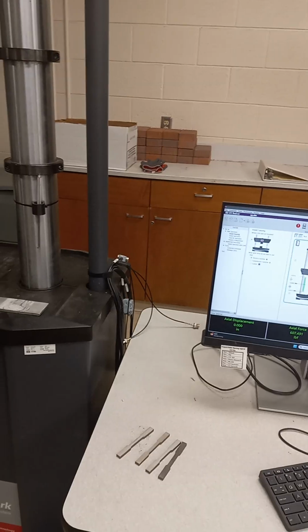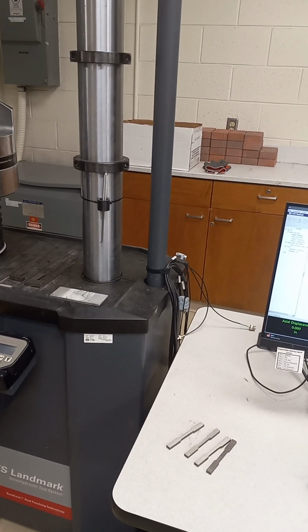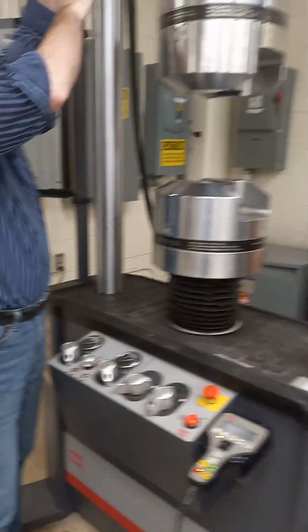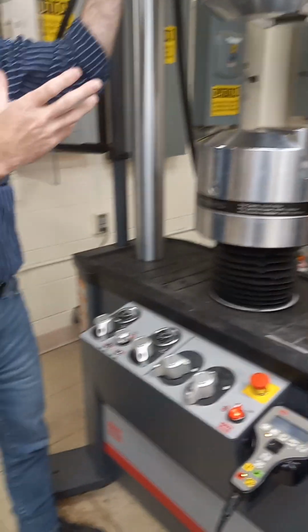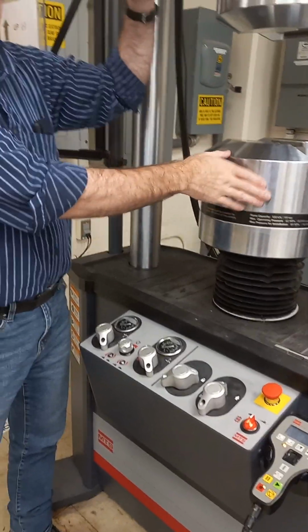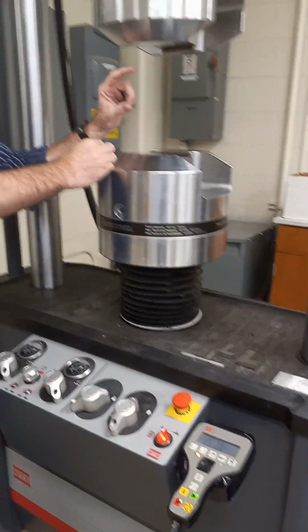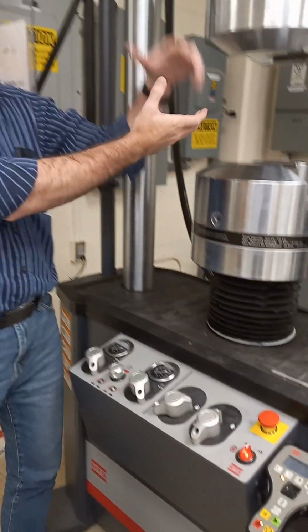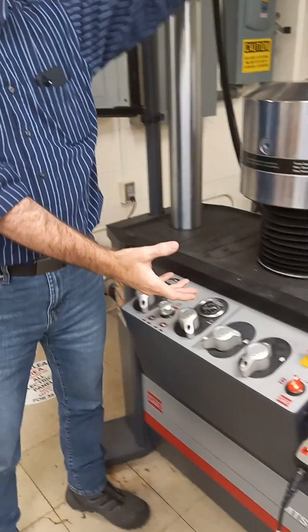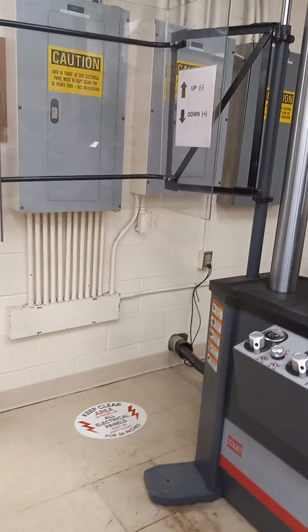And as you're pulling down, you're compressing these guys and pulling on this load cell. Anywhere that the machine can stretch, it will. So what we measure as far as how much is moved is not how much your sample has stretched. It's that much plus whatever the machine has stretched. So it's not true strain data, it's just how much the bottom head has moved.